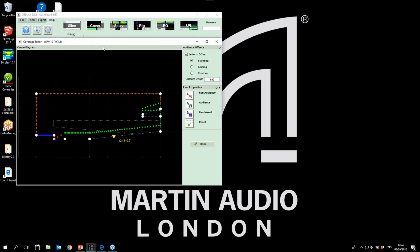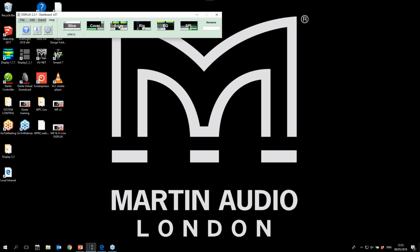So like I said previously, we can see that from the audience start to the audience finish is all considered an audience area. So we want to change the back wall to non-audience. To do that, we click on non-audience, and any area we don't want, we just click on the dashed line. And we now have a non-audience area. And then we want to change the top layer to seating. So we uncheck uniform offset, click the seating tab, and drop in on the dashed line, and we can see that dropping down now. And once we've achieved that, we just hit done and move on to our display tab.